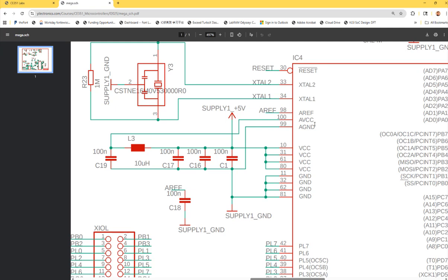If in the interview, people ask you, hey, what kind of ADC have you used, and you tell them, I have used the 10-bit ADC from the Arduino microcontroller. Okay, what's the resolution? 10 bits. That's the only answer you want to give them. Nothing else. 10 bits is the resolution, the standard answer to that question, and definitely there will be 2 to the 10th steps to resolve that whole range.